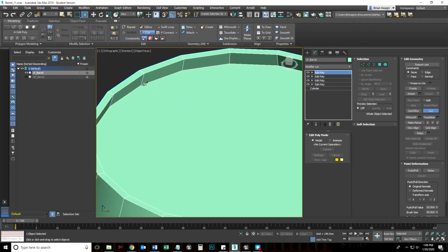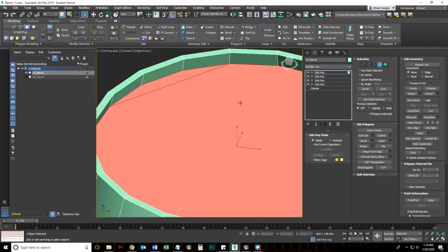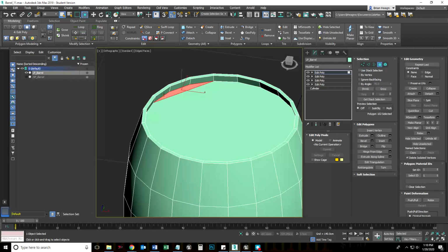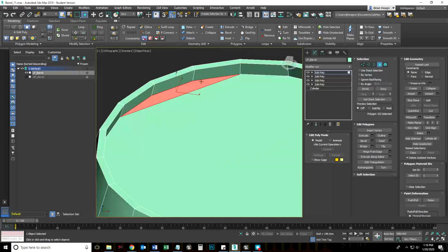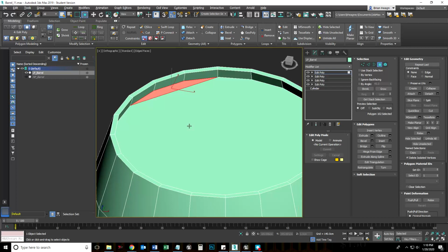And what I'm going to do is make four-sided polygons, and I'm going to go ahead and start with this. So this is going to be one side, two sides. I'm going to click here on that vertex, and I'm going to click over to here and left click, and then right click to disable out of that cut, and then I'm going to right click one more time so I can go into polygon mode and just show you that I have this selected and this selected. And this is a quad, four-sided polygon. Okay, we can do that again.